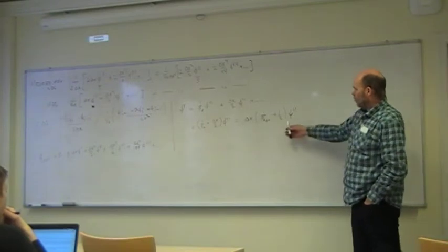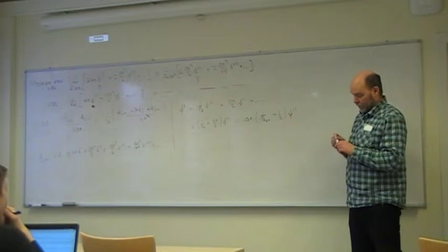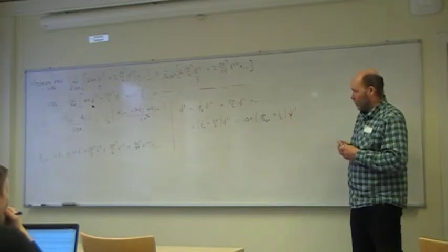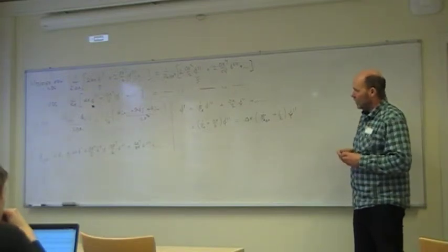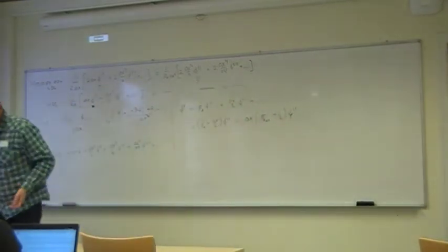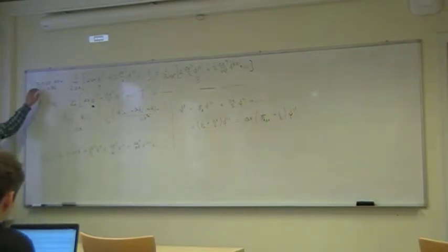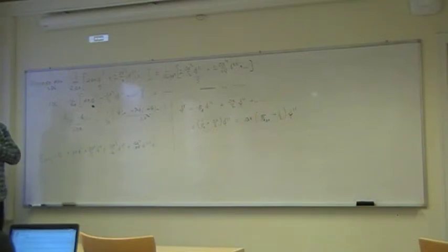So this 1/2 here is going to kill anything. Physics, real physics in this problem. So of course, you should never ever use this first order upwind scheme. It's stable, yes, but at a terrible price. So using a modified equation here, you can see what is going on.